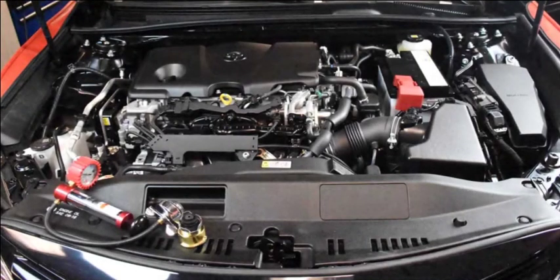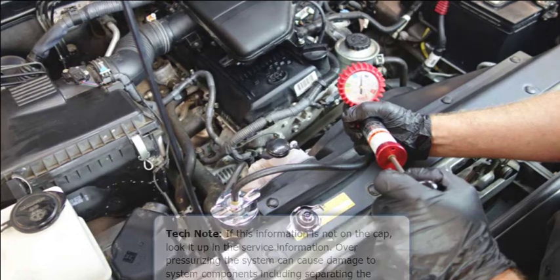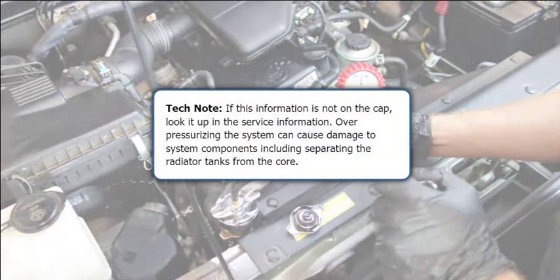Isolating the cause of the leak can usually be done by using a coolant pressure tester. Fill the system to the normal range if required, and install the pressure tester on the cooling system using any adapters if necessary. Pressurize the system only to the pressure indicated on the radiator or cooling system cap. Tech note: if this information is not on the cap, look it up in the service information. Overpressurizing the system can cause damage to system components, including separating the radiator tanks from the core.